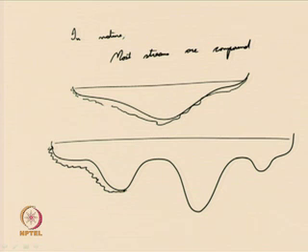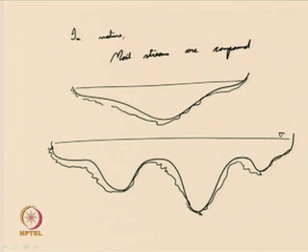There can be cross sections of river beds of such nature, typically witnessed in meandering rivers. For example, if you go through the Brahmaputra river system and take a bathymetric study of the bed using hydrographic survey, one may witness such cross sections where more than one main carrying channel is present, and some side channels may also be present. It may be quite possible.